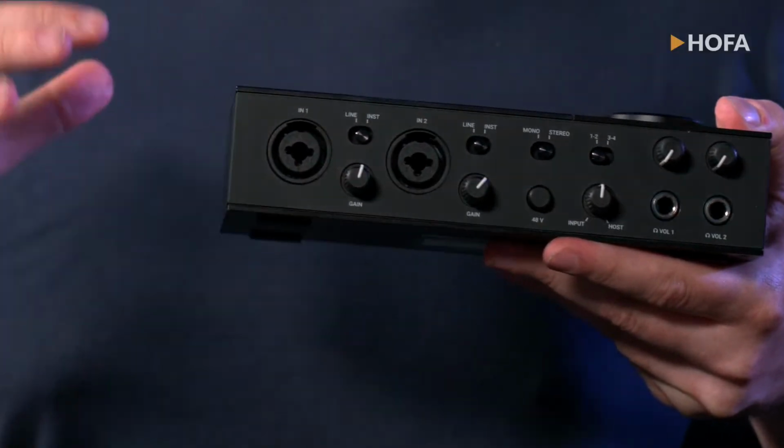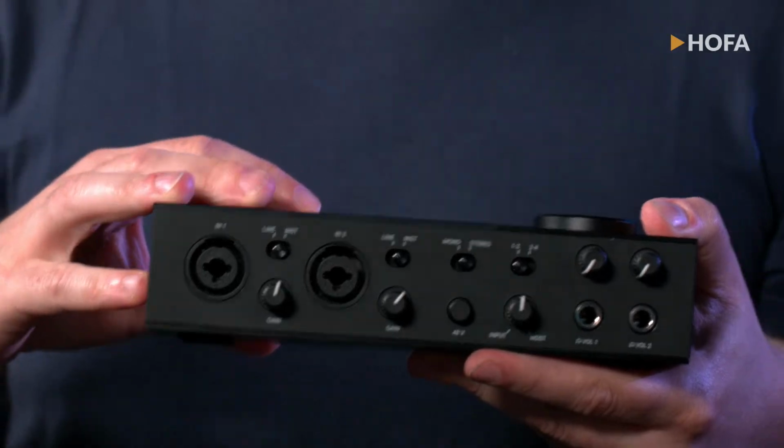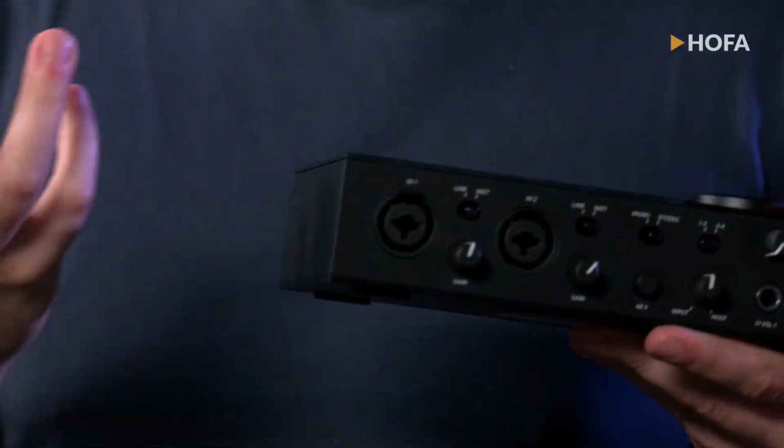You can either do it on the device itself, or if you have a more advanced audio interface like RMEs or Apollo, even more, you can also sometimes do it in the software when you have a control panel, and you can adjust the gain in your digital control panel for the analog device. But usually you can do it by changing up the knob's position and bringing something like a microphone level to an actual level to work with, to a line level to go on.